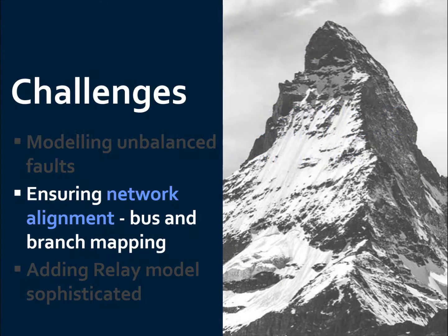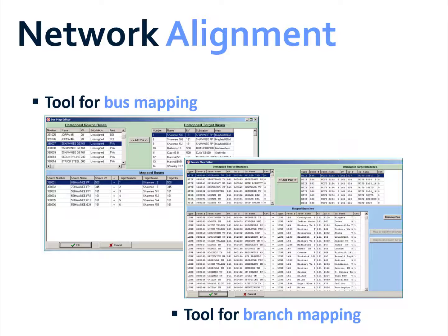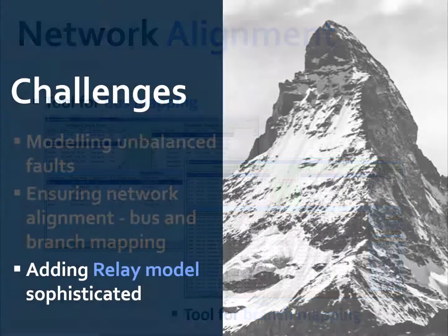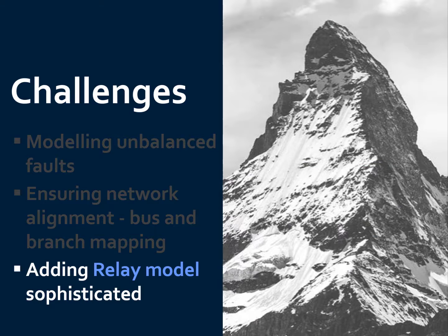There also needs to be alignment between the network models in the system dynamics and protection simulators. The alignment of these models can be complicated by the use of detailed bus structures in the protection simulator, for example, breaker and a half and ring buses. A sophisticated protection system model is also required, and not simply an abstraction of the main protection elements into generic